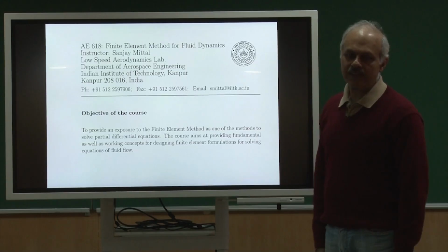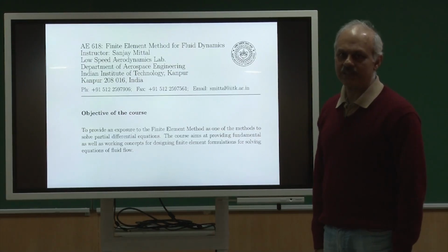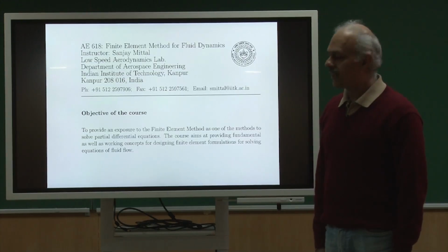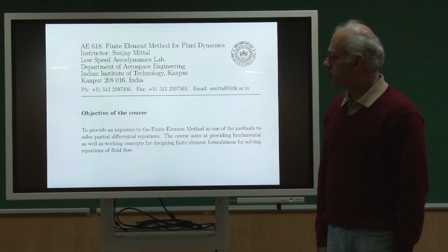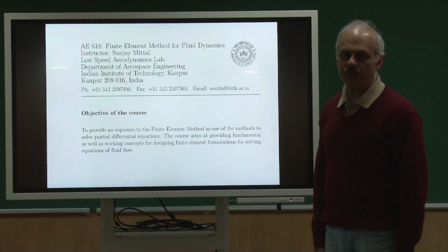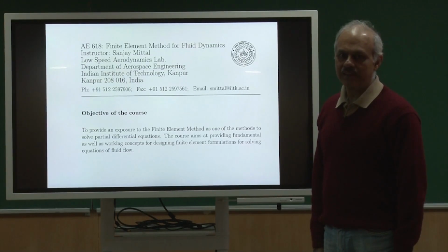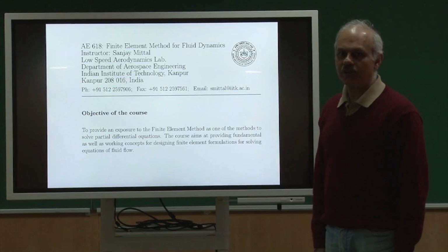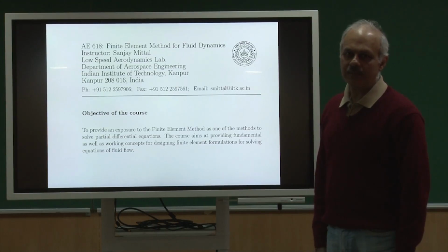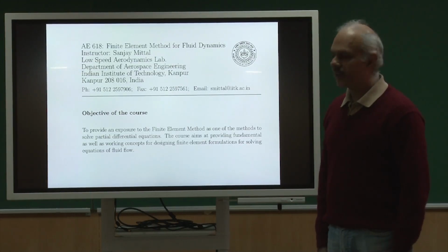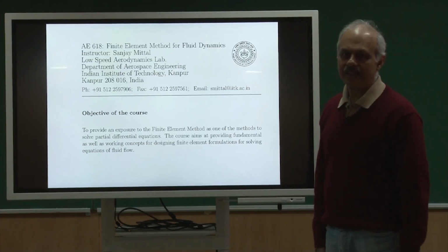Now obviously when you are interested in a numerical solution, some kind of approximation will be involved. So there will be an error between what the exact solution is and what you would predict numerically. Most numerical methods talk about error control, and in fact the philosophy of how the error is to be controlled is what distinguishes one numerical method from the other. There are a host of numerical methods and finite element is just one of them.